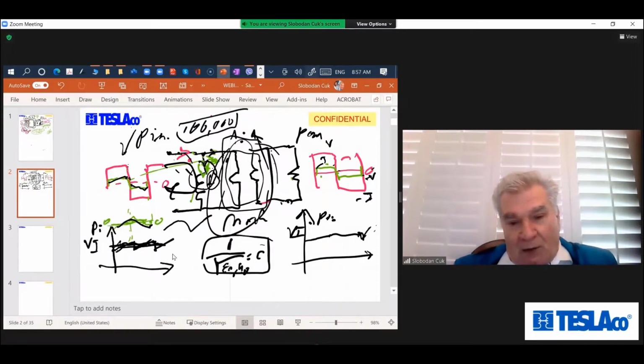you go out on the internet, you'll find people tie themselves in knots trying to explain how the transformer works and so on, because they look at Faraday's law and at all the other ways you can induce a voltage, not only by a moving magnet but by changing the geometry of the circuit and changing the magnetic flux, getting it at a certain angle to the loop.